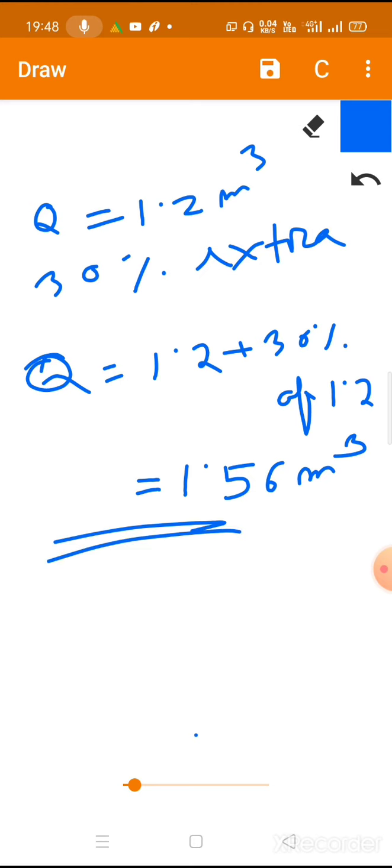So now this is the total quantity of mortar that we require, but this is the total quantity of mortar after mixing cement, sand and water. That means this is the total quantity of wet volume. But we do rate analysis in dry volumes. Whenever we are going to buy the items from the market, we will have to buy them as dry items. So ultimately we need to find out the dry volume, isn't it?